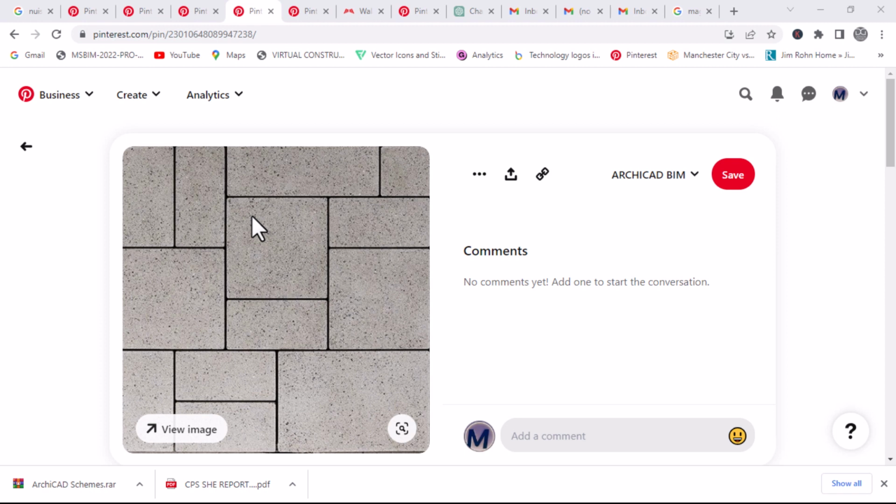You're going to start by having a base which is going to be rows and columns. So if you dissect this into some rows and columns, we have this line as a column, another column, another column. There we go, column, and then columns. For rows, we have this horizontal line as a row, this line also as a row, this one also as a row, and then we have the row here, lastly another row there. But it seems like these rows are equal in terms of the height, and then the columns also are equal. I'm going to make them 400 each.